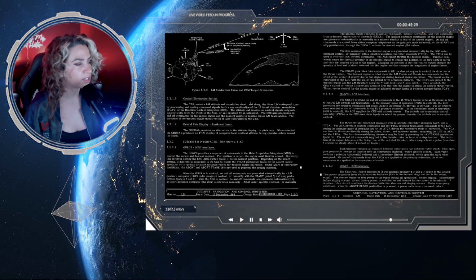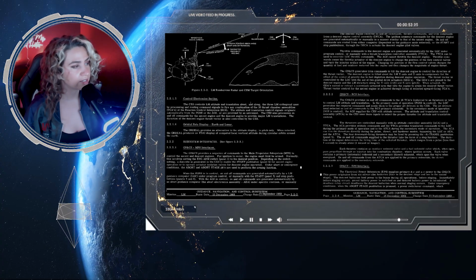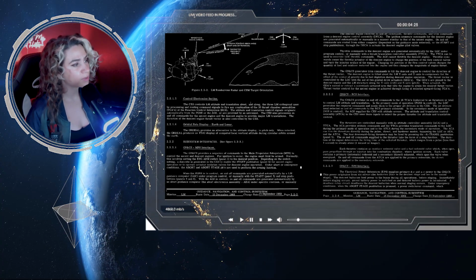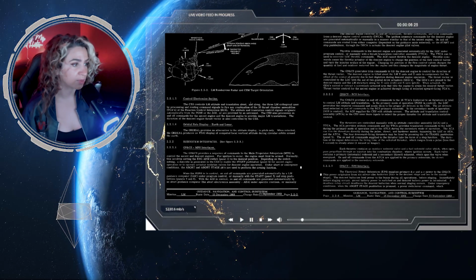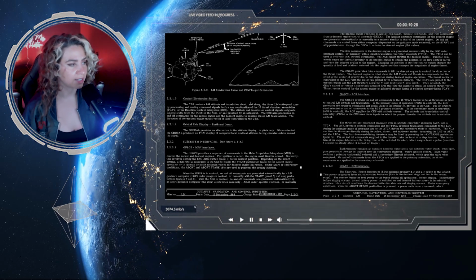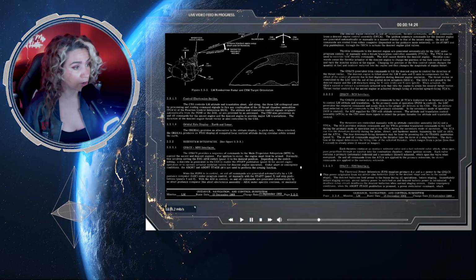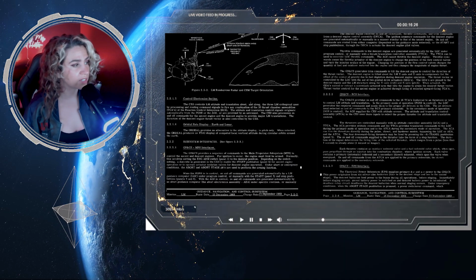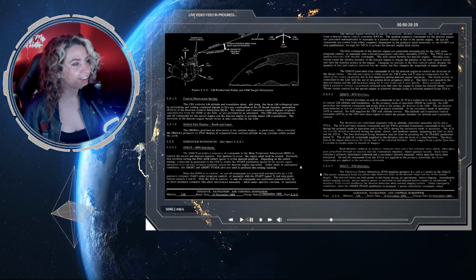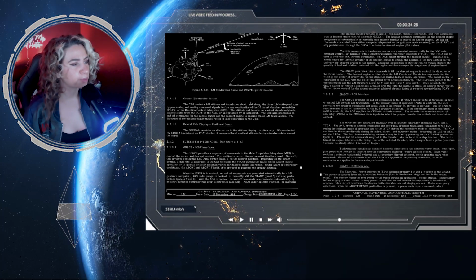Subsystem interface, GNCS, MPS interfaces. The GNCS provides a sequence of commands to the main propulsion subsystem, the MPS, to control the ascent and descent engines. For ignition to occur, the engine must first be armed. Normally, this involves setting an ENG ARM switch, panel 1, to the desired position.